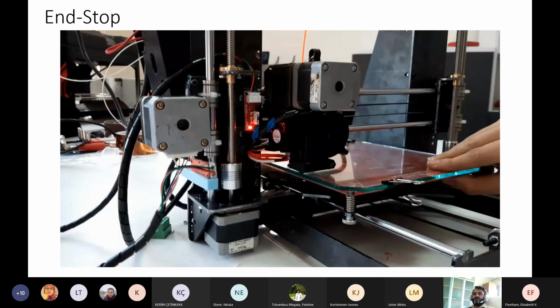Another important control used in these printers are end-stop switches, which determine the limits of the axis. When the extruder head is shifted to the far left corner of the printer and reaches the end stop, it records this as the leftmost position of the table plate. From this position on, the axis movement along the distance of a certain axis is counted by steps of the stepper motor, and the position is monitored. Of course, this procedure will usually need to be recalibrated after each print.